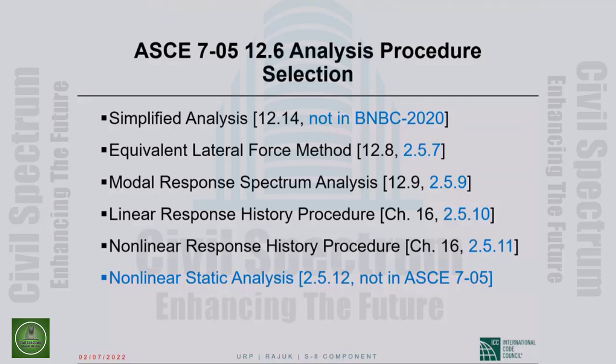Linear response history analysis, I do not believe, gives you anything that you cannot get out of modal response spectrum analysis, so I personally am not very high on that. Nonlinear response history analysis, on the other hand, is pretty much the state of the art. That's about as far as we can go with analysis.